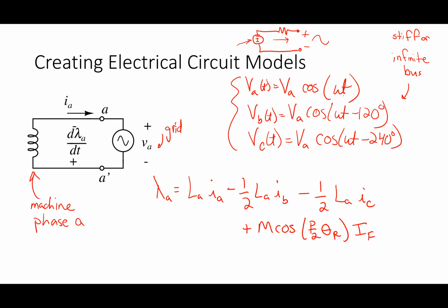It has a phase shift from the voltage, right? So in general, I have a power factor angle. So IA of t would be IA cosine omega t plus phi, and they would all have that same phi, right? I don't want to write all that out, it gets ugly.